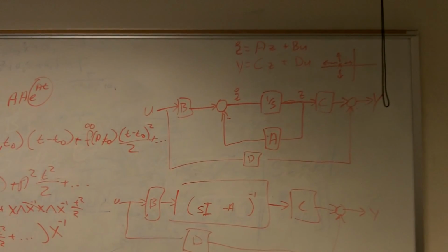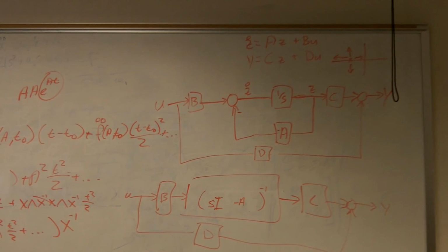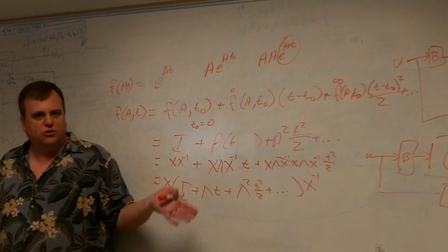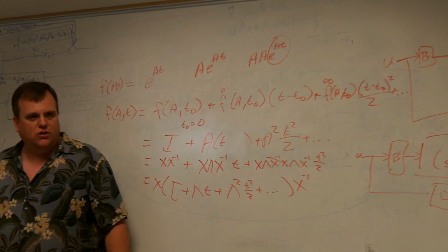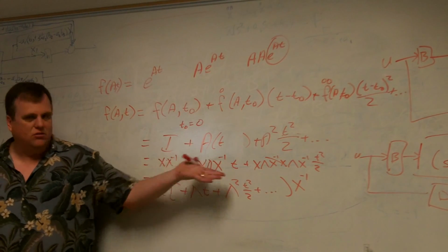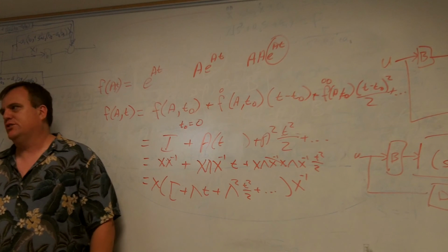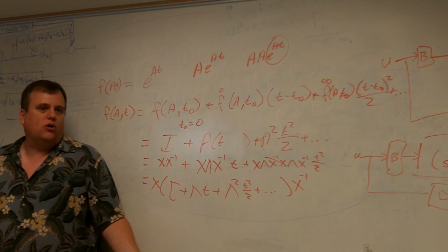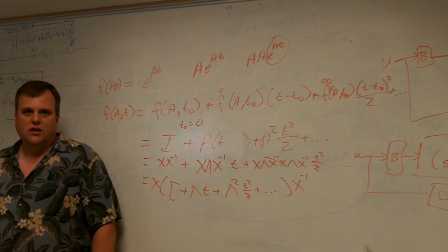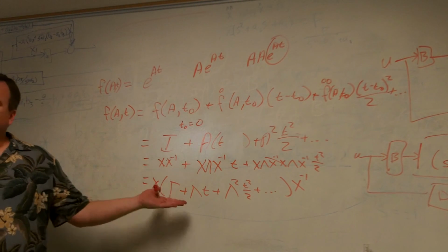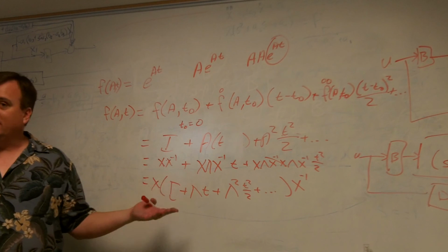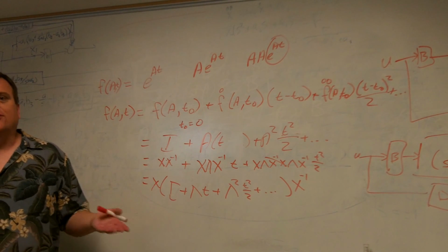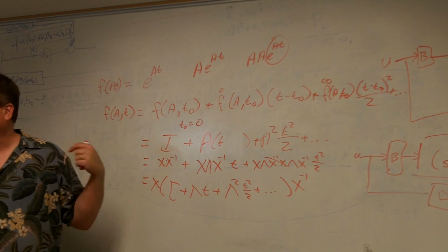Okay? If it's nonlinear, z enters as a square or something like that, then you now have to deal with nonlinear equations as it goes. But as long as it's linear like that, I've got all kinds of tricks up my sleeve for it. And we can do things in parallel, we can speed it up like crazy, all kinds of great, beautiful things. And everything that you did before still applies, the intuition, as long as we've shown the eigenvalues are the same as the poles. As long as the eigenvalues have negative real parts, it's got to be stable.